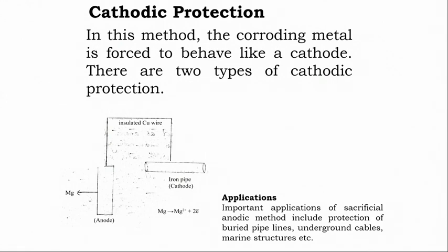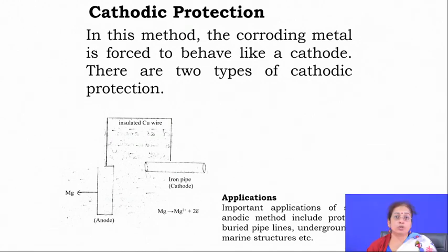Whenever the anode is subjected to corrosion, naturally there is evolution of a lot of electrons, and whenever those electrons are evolved, your cathode is highly protected. So, your metal is highly protected, since it is acting as cathode anyway. So, there is no corrosion at all. This is a very important way of protecting the metal from any kind of aqueous corrosion.